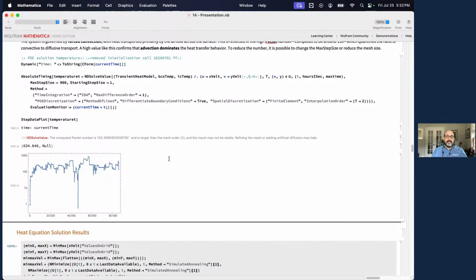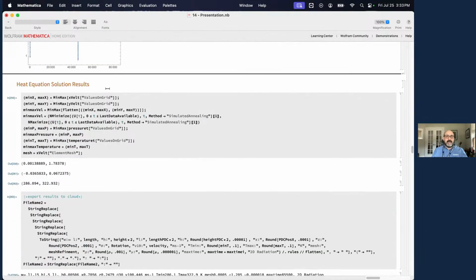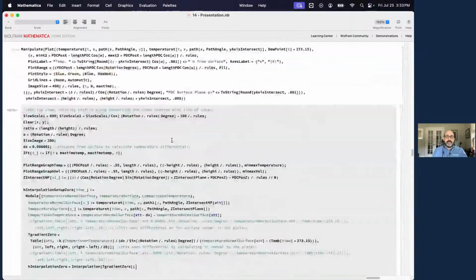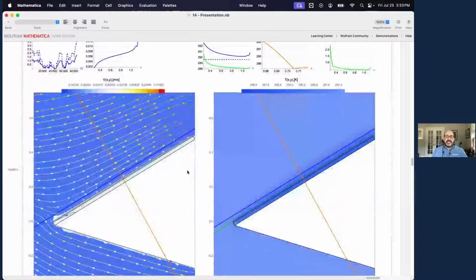And you can see already the progress. If you have more than 3,000 elements, it's going to multiply by the number of elements you have. So if you have 3,000, 1 day. If you have 6,000, 2 days, etc. That's why the optimization of the elements is so important when you have complex problems. Okay, so again, I take my solution. I don't want to be wasting any time, so I save my solution so I can reuse it later. And then eventually I get to visualizing the data, and this is the data.